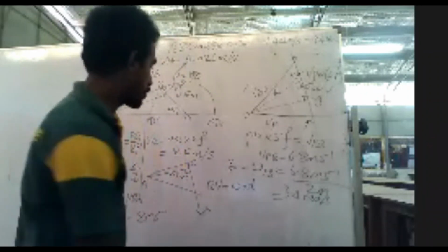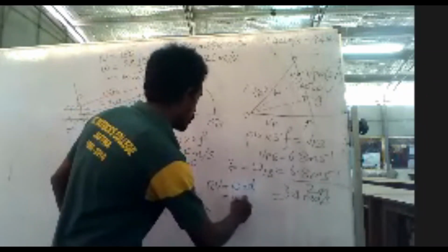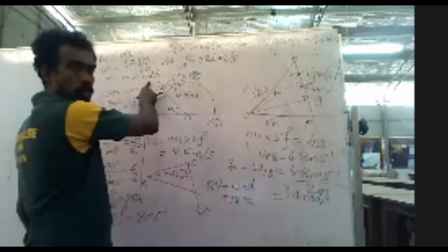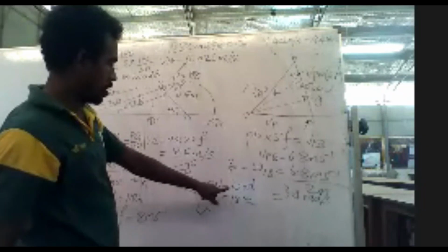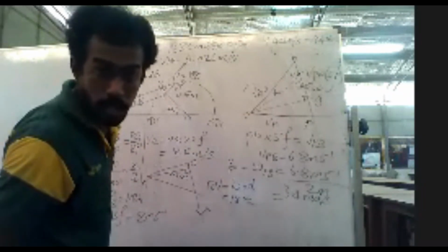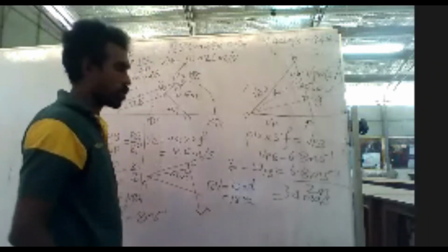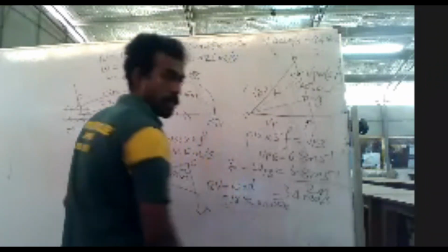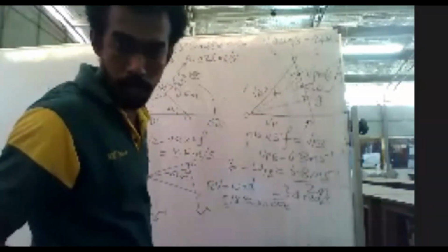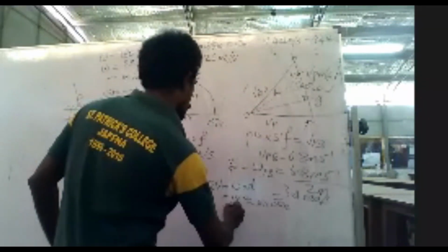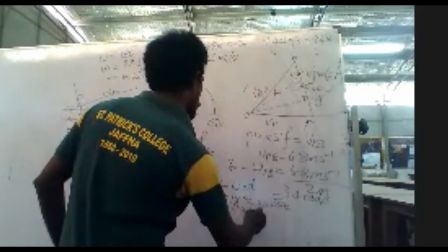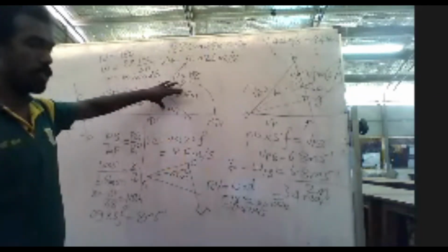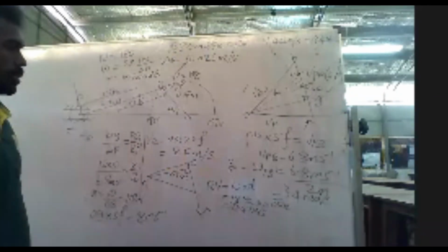So that is equal to 18.82, that's the omega of the crank, into R, that is given as 50 millimeter, that is 0.05 meter. That will give you 0.47 meter per second. Right? So rubbing velocity of crankshaft is 0.47 meter per second.